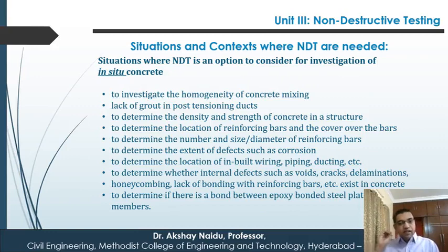Situations where NDT is an option to consider for investigation of in situ concrete: to investigate the homogeneity of concrete mixing, lack of grout and post-tensioning ducts, to determine the density and strength of concrete in a structure, to determine the location of reinforcing bars and the cover of the bars, to determine the number and size and diameters of reinforcing bars, to determine the extent of defects such as corrosion,